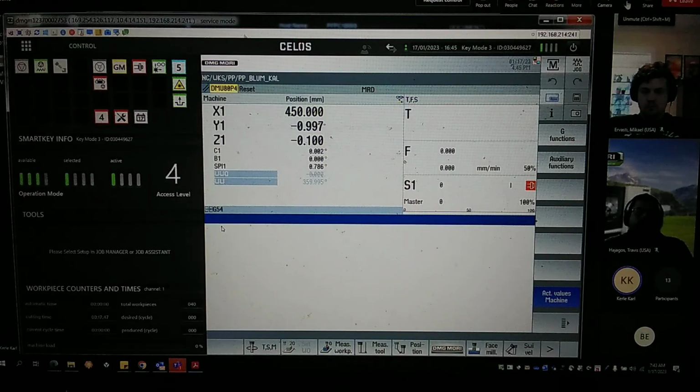The edge finder is an exception when you would like to use it, because you must have a direct connection, or you have to look directly at the tool itself. Why? Maybe because of a gray, darker window on the working area door, like a milky glass, you cannot really recognize whether the position is correct or not. So this can be used with the door open.